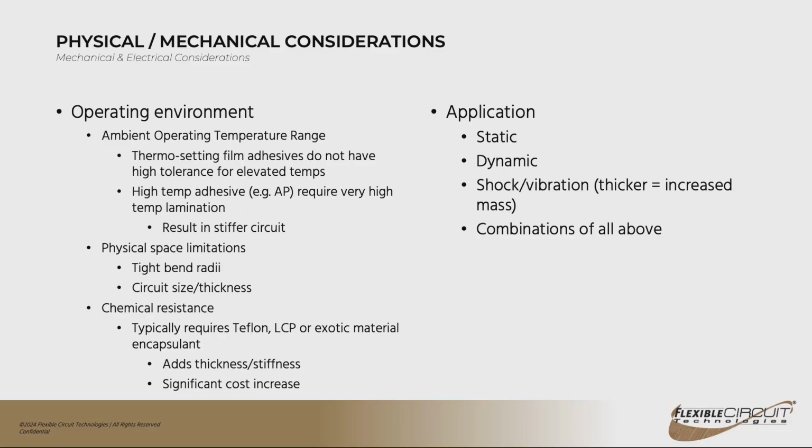And as far as the application, static versus dynamic, when you look at your static applications, are you going to be able to form it the way you want to so that it'll fit? If it's dynamic, it's going to have to be ultra flexible. You're going to have to take into account neutral bend axis and things like that that really don't play nicely with impedance control and other things like that. So those are all going to have to be weighed. If you have high shock and vibration applications, if you have a thicker circuit, it's going to be increased mass and it's going to be much more impacted by any kind of shock or vibration. And combinations of all of these features can certainly come into play and cause issues.